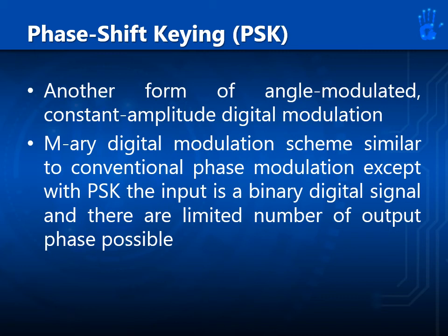Lastly, we have phase shift keying, or PSK. PSK is another form of angle modulated, constant amplitude digital modulation. It is a digital modulation scheme similar to conventional phase modulation, except with PSK, the input is a binary digital signal and there are a limited number of output phases possible.